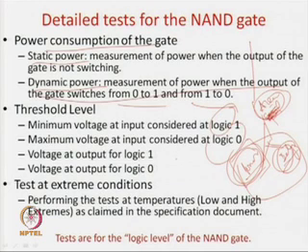Generally, we can say that in a circuit where 5 volts is considered the upper threshold and 0 volts the lower threshold, anything above around 4.8 volts up to say 5.2 volts we can call logic 1. And for logic 0, if the voltage is up to say 0.3 volts, we call it logic 0. So, in this specification, if I get something less than 0.3 volts or below, I call it logic 0, and from 4.8 volts to 5.2 volts I consider logic 1.